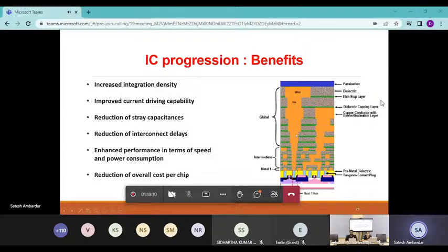When I talk about the initial layers, because the transistor structures are very thin, the initial contacts are very small and very thin, as these have to be interconnected with the transistors, which are also smaller in size. As we go above the metal layers, the global interconnects are relatively thicker, longer, and widely spread. The interconnects between the different metal layers are called the vias, and these are basically the copper interconnects and the metal layers. Finally, the passivation layer protects the die, and then we have the packaging, where the pads are connected to the outside systems.